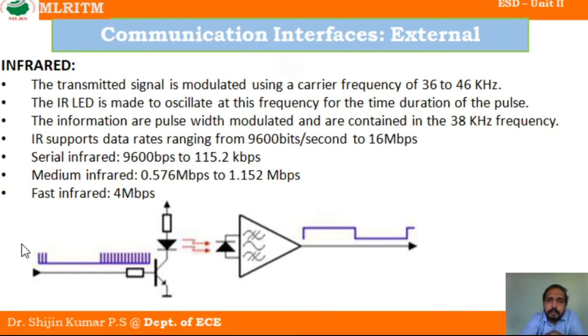The information is pulse width modulated and contained in this 38 kilohertz frequency. So what is the type of modulation that we are using here? Pulse width modulation.